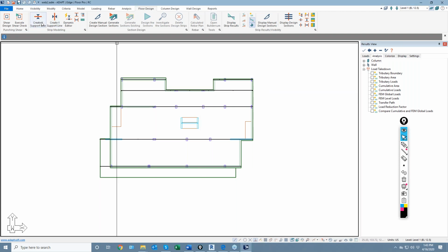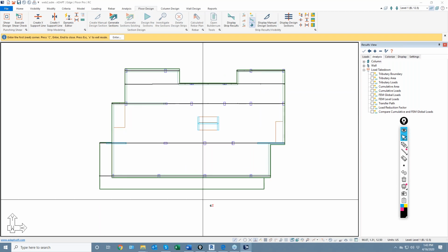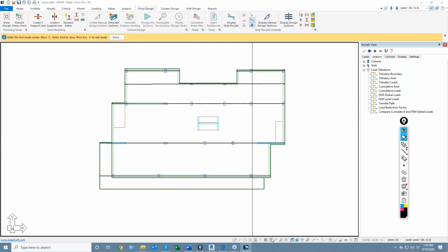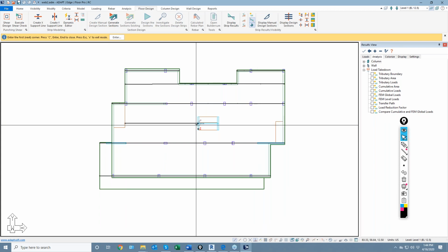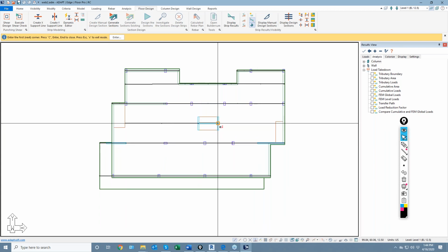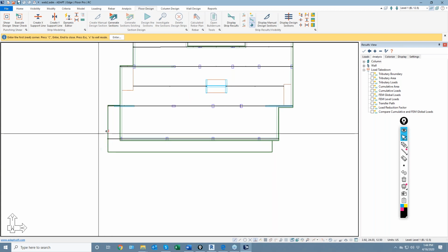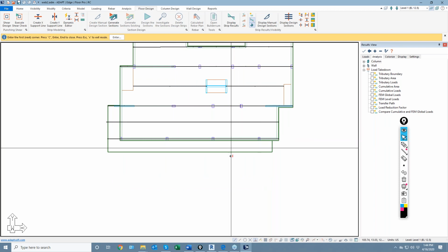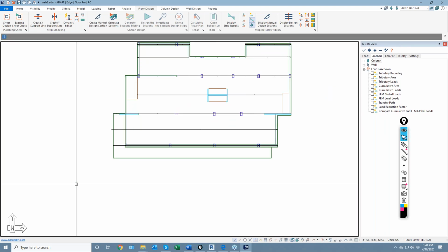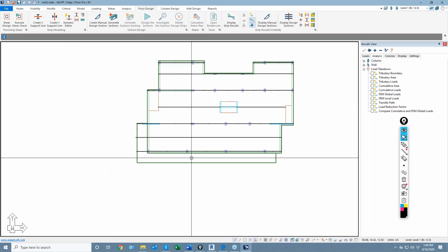Okay, so I'm now going to just go ahead and introduce some middle strips. This is just really free form. It just is required by the user to enter a design strip for the middle strip. So we're going to go back, use some of our snap tools, and I'll just go in and enter a middle strip from here over to that point. Maybe from there to there. I'll add another middle strip along this path. Okay, and I'm also going to add a splitter right here.